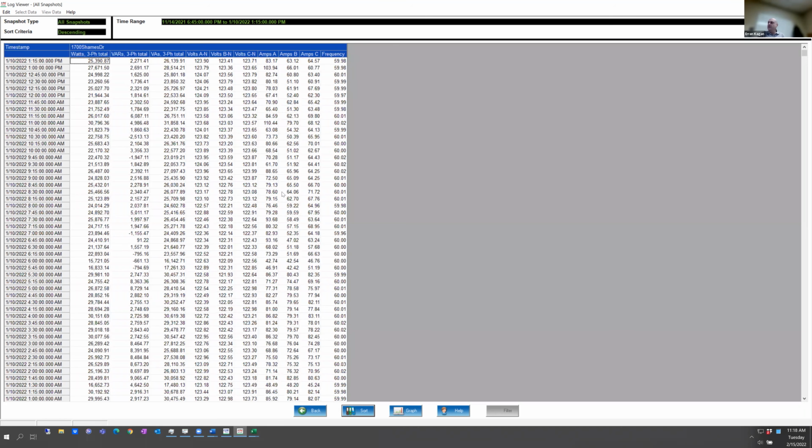Anybody have any questions, Chris? Yep, we have a question with regards to the system events log. So if there is a change in the device profile by someone or a new profile downloaded at some point, is that captured by the system events log? Yes, in every meter we made. So if anybody tries to do a password change, a new profile especially, a demand reset, an energy reset, any changes to the meter, anytime somebody communicates with the meter and does an action, download a log, upload a profile, reset anything, it's all logged in system events.